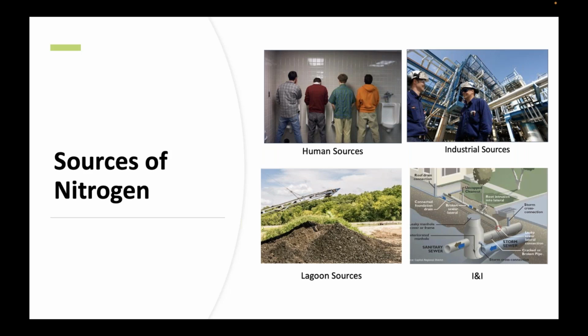And if you're a municipal system and you have an industry feeding into your influent stream, that could have an impact on the amount of nitrogen that you have coming in. There's infiltration and inflow. Every wastewater collection system, especially municipal, tends to have infiltration. You're probably familiar with it. That's where the groundwater, or the water around the pipes, seeps into the pipes themselves. This is particularly seen when you have high rain events and it spikes what's coming in. Well, what's in that water ultimately ends up at the plants as well.